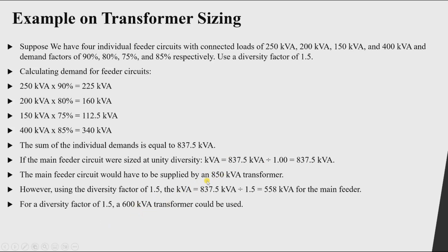Okay, that's why the demand and diversity factor, or simultaneity factor, are very important in sizing our transformer, in sizing our cable, and even in load estimation, as we will see in the next lesson.